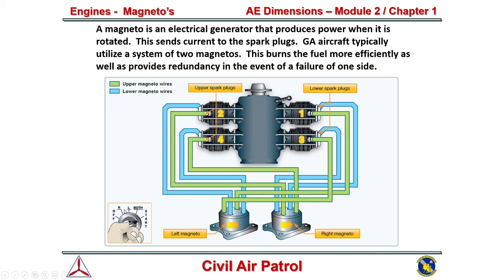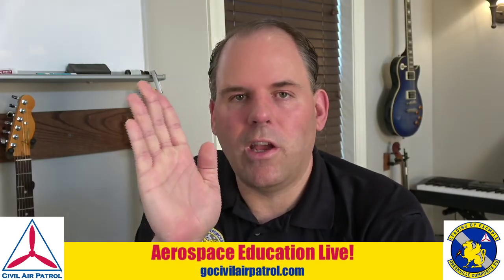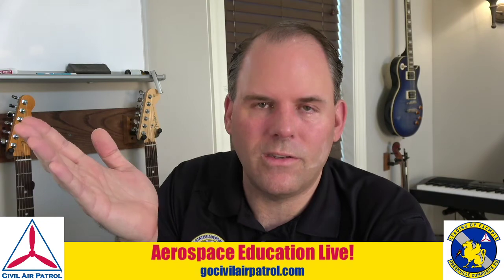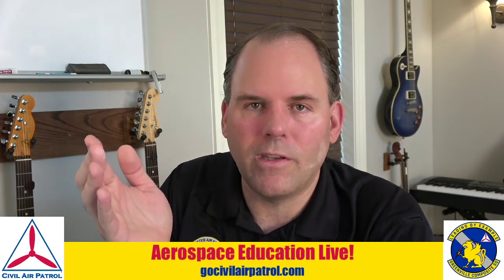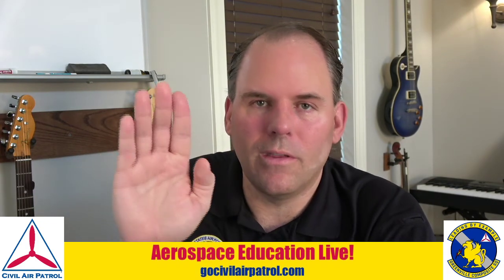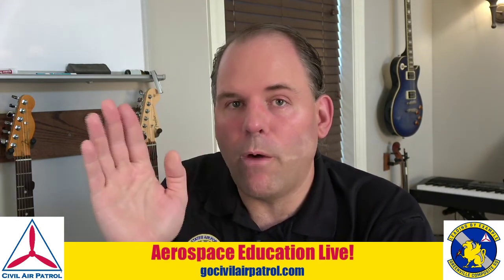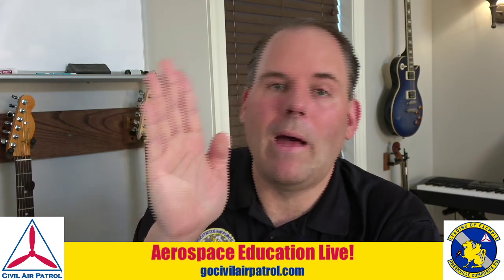And then you're going to look at the RPMs. You'll see the RPMs in your aircraft come down a little bit. Again, this assumes you're in a fixed-prop aircraft, so the prop doesn't change. But you will see the RPMs come down. Now, what you want to look for is that they don't come down a lot.